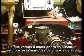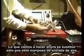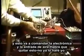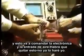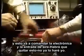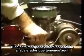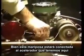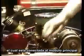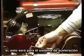Now, what we're going to do now is that this is going to be replaced with this air gate, as you see right here. Okay, so that's going to regulate. I better turn it up right. And that'll regulate our air going in. Does this come off like this? Yeah, it'll take off. Now, the air gate will be hooked to the accelerator, the laser accelerator we have here, which is hooking to your computer system. You're going to take this rod, you're going to hook it right up here, right? Yeah, and that'll be for acceleration control.